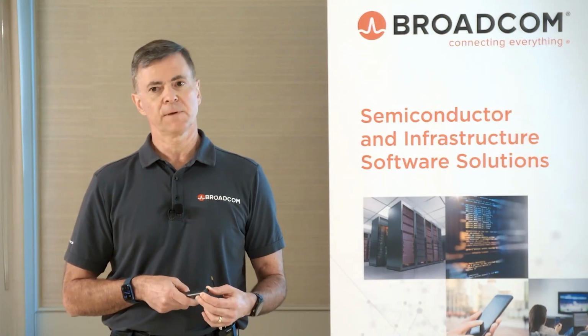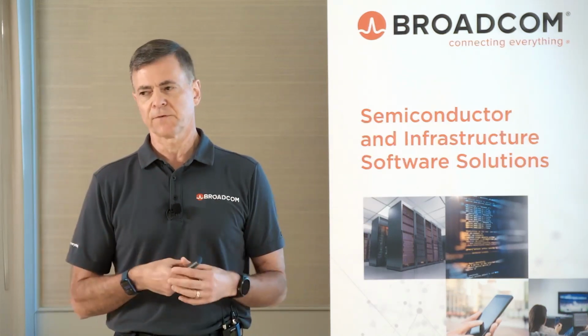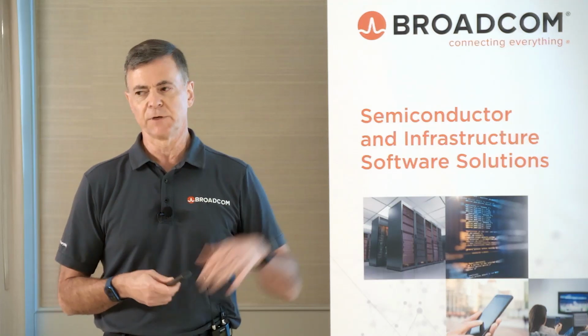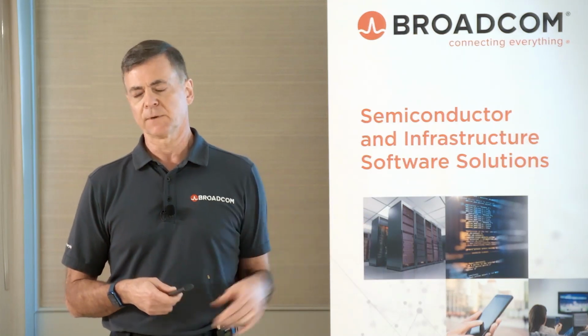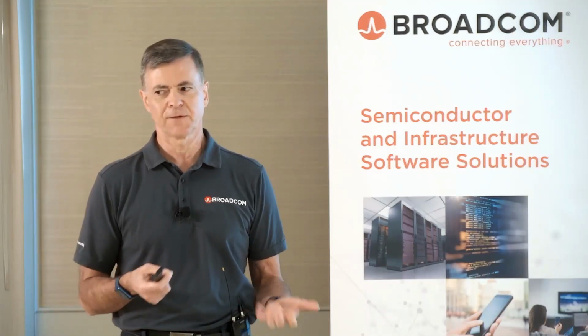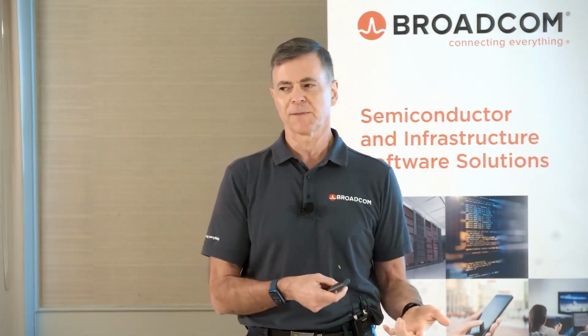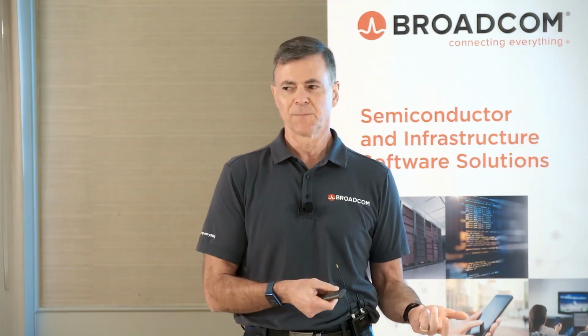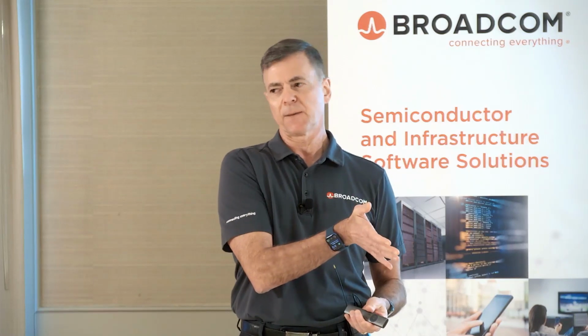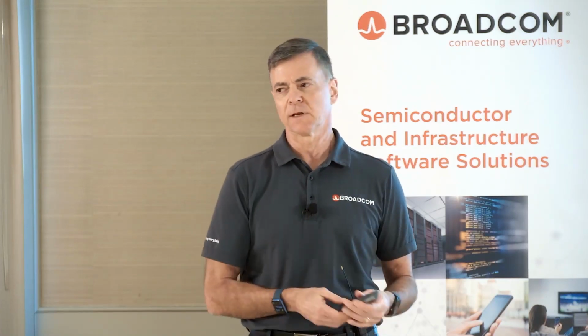I mean, if you look at the whole switch box, if it was, say, all copper versus an all optical solution, it could be double the power with the optics. Okay. Yeah, I mean, that's a key thing: there's a lot of focus on the switch silicon itself, trying to minimize the power of the switch silicon, but you don't realize that over time more and more power, more and more cost is moving into the optics. Right. And that's really been a continuing trend.